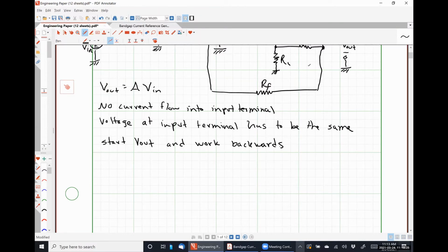And the second trick is normally nodal analysis will be your friend in these. It's kind of hard to use mesh or KVL. So normally you want to do this all in terms of currents. Not that that will be the only thing that you ever do, but typically try that first and it'll help.